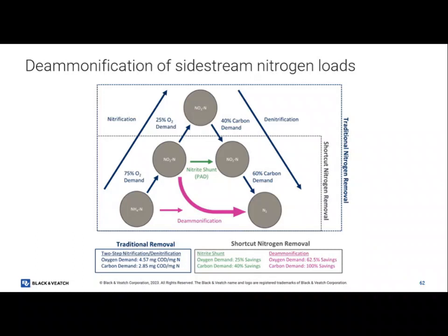And that's really where Cruise leverages that low DO. Because they might have 0.5 DO out here, which means they can get to 0 in the middle. But if I have 5 DO out here, this isn't going to be anaerobic. That DO will go all the way in the middle. So that's where that low DO starts to have better performance because you can start to create these stratified layers. But 5 DO, it's hard to make it. All of this is going to be homogeneous because the DO is so high. It's all going to be aerobic. You're not going to have these little micro environments. So low DO really starts creating micro environments.